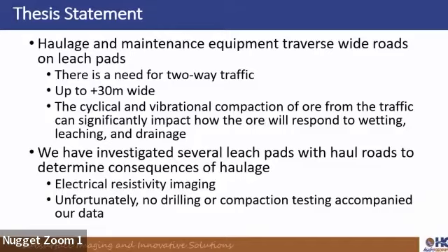Usually what we do is we come in and do the electrical resistivity, give the data to the client and walk away. So we don't have any ancillary information from drilling or compaction testing to verify what we have seen with the electrical resistivity, but we've done this a long time and we kind of know what to expect from our data.